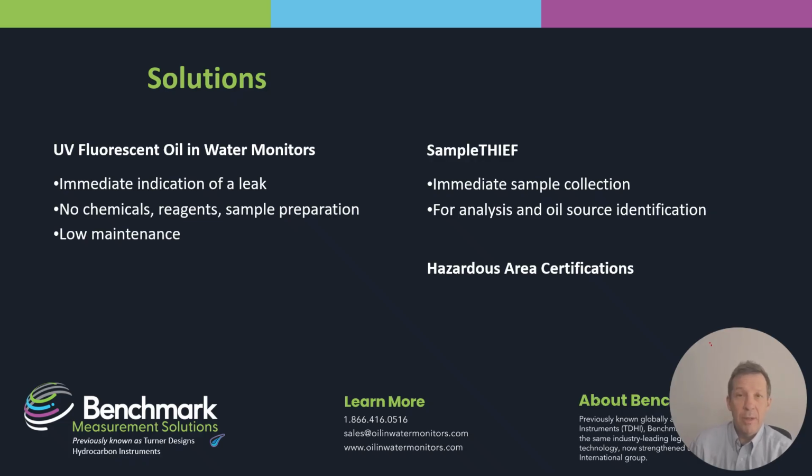With a sample collection system, operators will know what type of hydrocarbons are in that water to identify the potential heat exchangers for the leak source. And hazardous area certification is available for both fluorescence instruments and the SampleTHIEF.